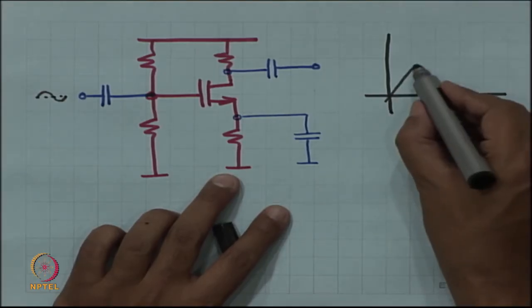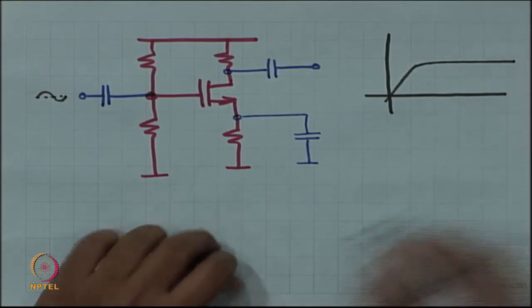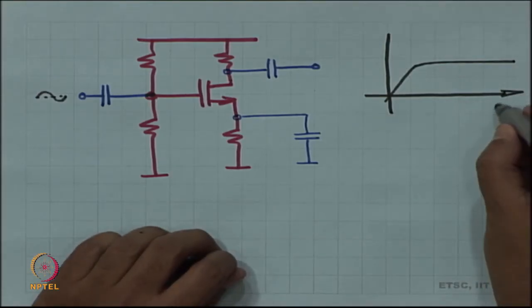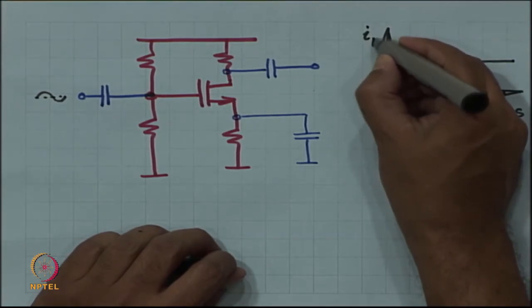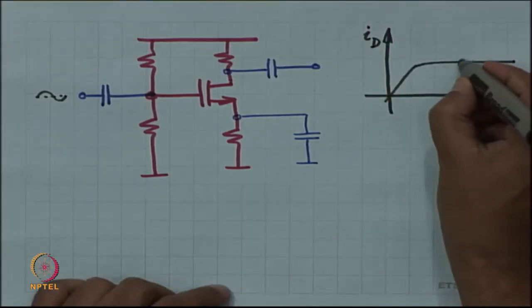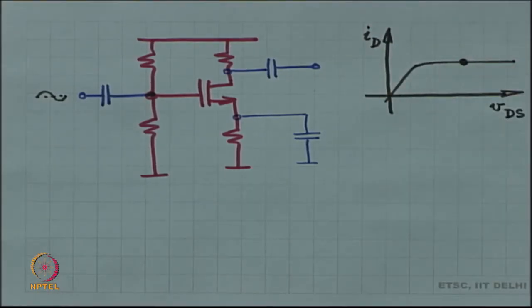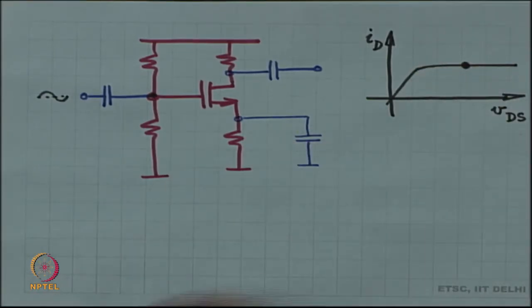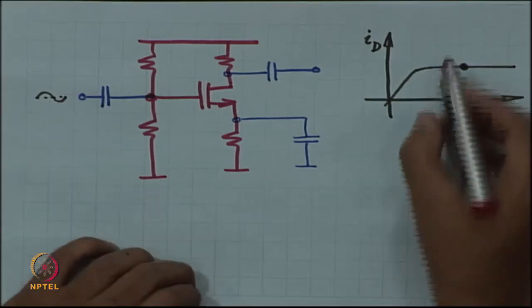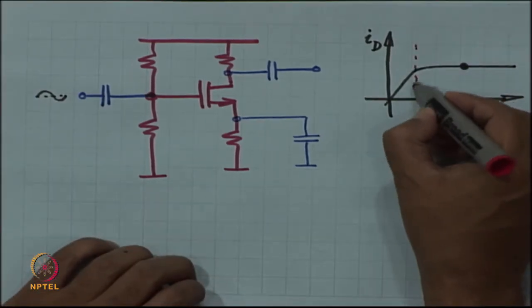So, remember you had set the MOSFET at an operating point, right, but you need to remain in the flat region of operation, otherwise the slope of this line is going to become low and therefore, the gain is not going to be enough and so on and so forth. So, the largest change